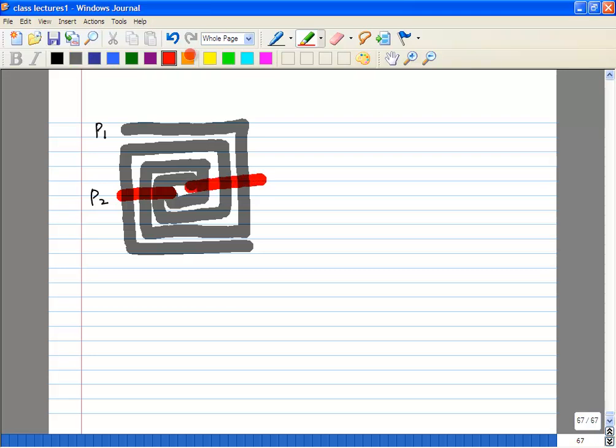So you want to take this across like this, and this would be your S1 and S2. This is fairly symmetric. You get the basic idea, right? So you have the same number of turns on both the primary and the secondary. You have the same number of metal layers, same width, same spacing, and you have an underpass in the primary and an underpass in the secondary, all at symmetric points. Is that clear? So this is one kind of planar transformer. Let's call it transformer 1.